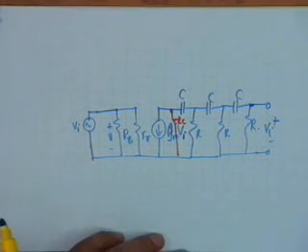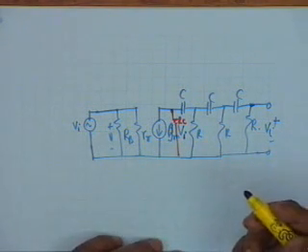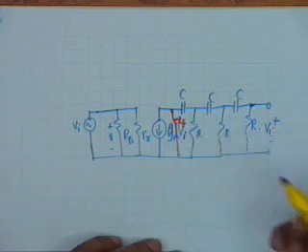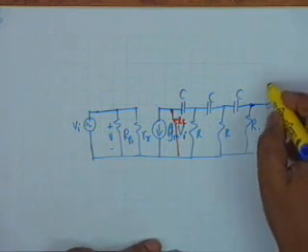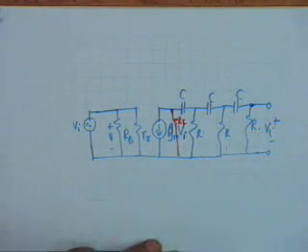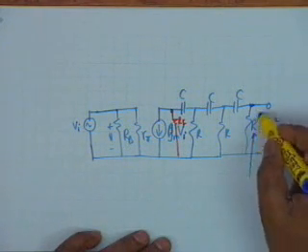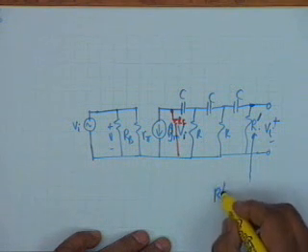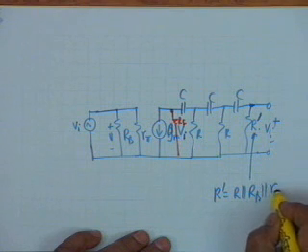This will give you the conditions for oscillation, and this condition shall not be exactly 1/29 and 0 degree. It will be affected by RC. And since this is going back here, you should, in fairness, shunt R by R prime, where R prime is R parallel RB parallel R pi.